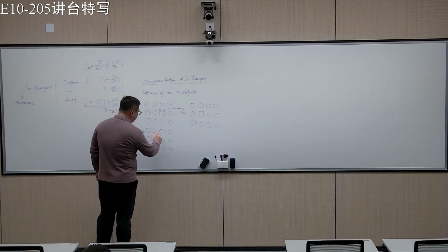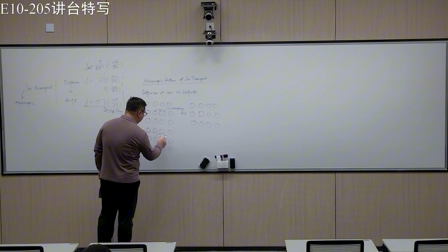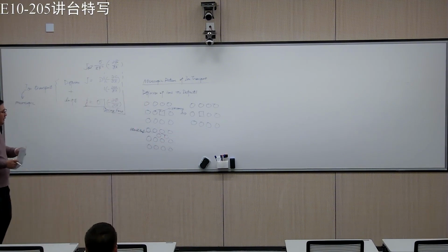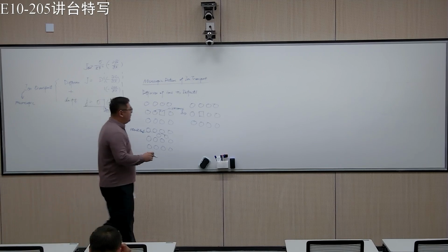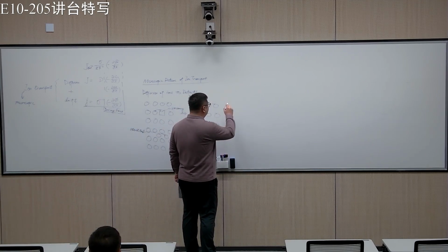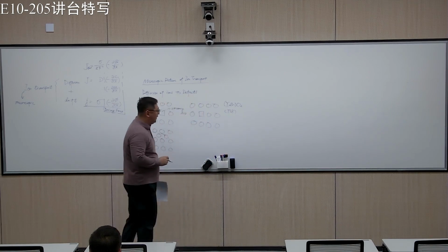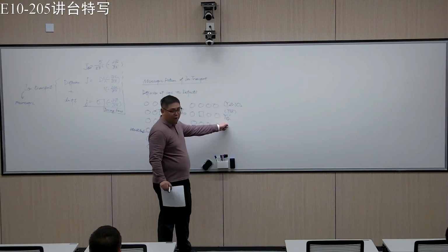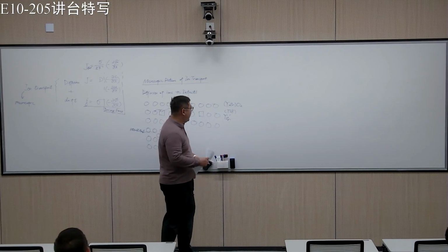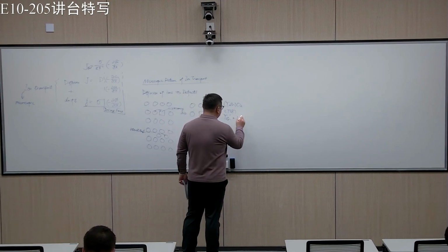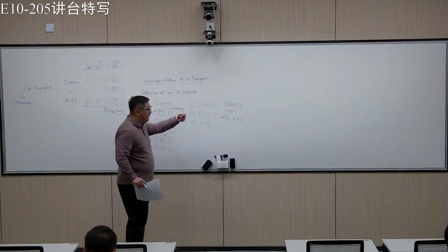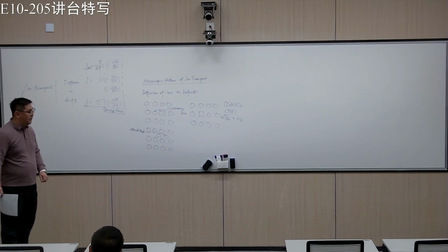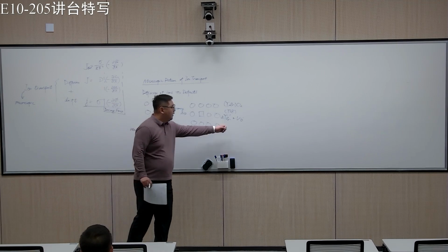So it can jump from here to here. Okay, I'm now drawing another picture. I'm just showing in this. Okay. So the vacancy mechanism is very common. For example, if you have something interesting like zirconia, so-called YSZ, what you do is introduce dopants, 3 plus yttrium into 4 plus zirconium, then you essentially introduce oxygen vacancies. Then the motion or the diffusion of the oxygen is basically driven by that.